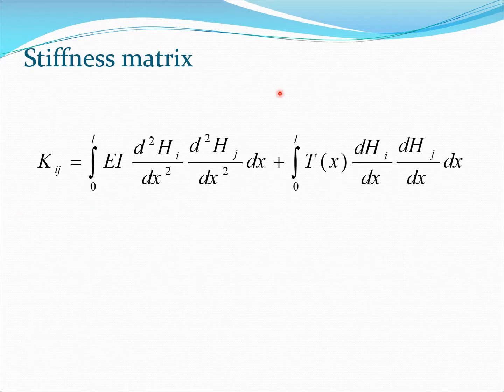So that's what we do here, and we write down this nice looking stiffness matrix here. And we clearly see that all these are terms which will exist because H was cubic, and so first derivative would exist, second derivative would exist. These will be all good terms mathematically, and therefore I can perform these integrations. So let us take a look at how to calculate some of these mass and stiffness matrix terms.